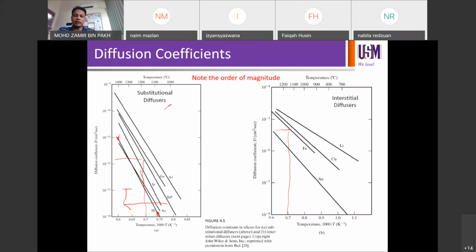So you need to avoid cross contamination of your chambers in all cases, at all possible cost. You may assume that you are diffusing phosphorus or boron, but you are also diffusing unwanted metals into the lattice. And when you check your result, something goes haywire. It's actually due to the metal incorporation in the lattice.